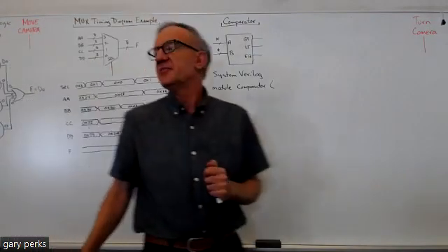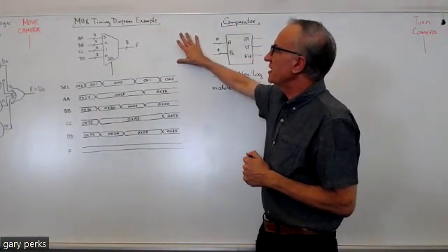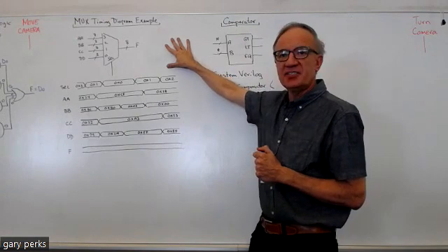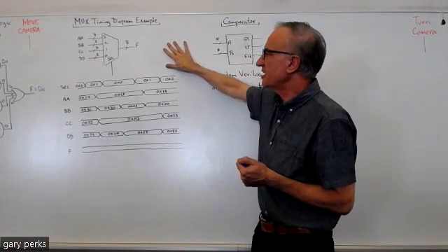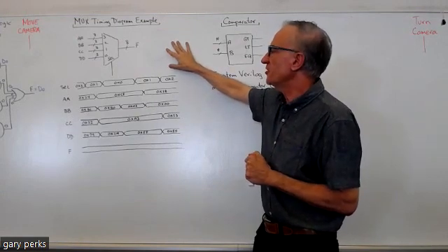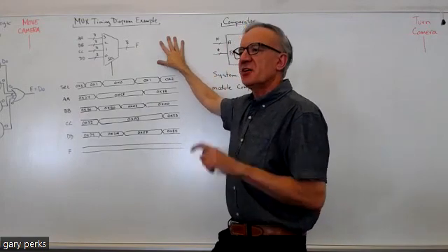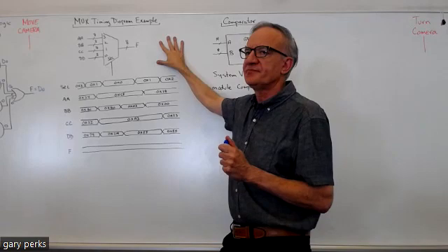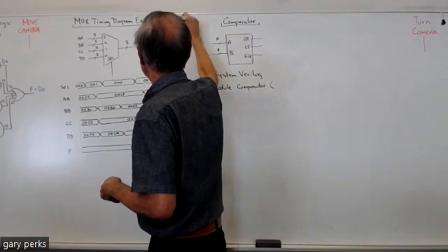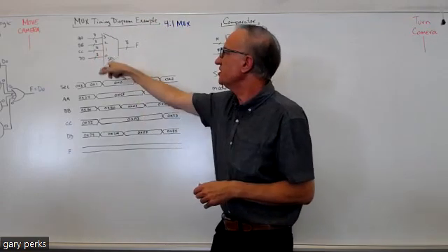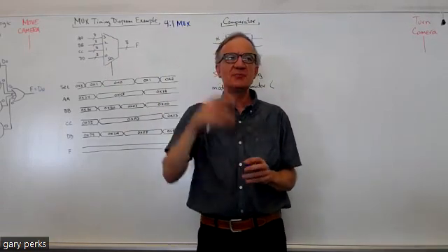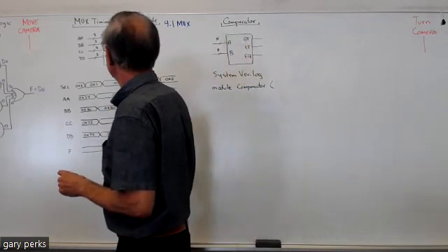All right, so the next thing is I wanted to show you an example of a timing diagram with a mux. And the activity today is doing something like this. So if you understand this example, then I think the activity should be fairly straightforward. So, okay, what kind of mux is this? So what to what? Yep, 4 to 1. There's 4 inputs, 1 output, and there's always 1 output. This is a 4 to 1. And you can see each input has 8 bits, the output has 8 bits. How many bits would the select input have since we have 4 inputs? 2.